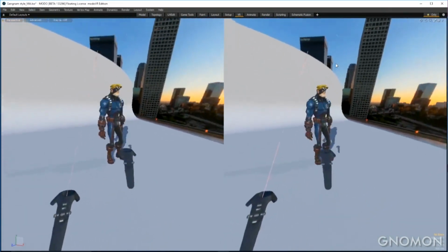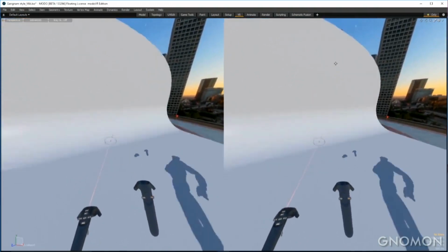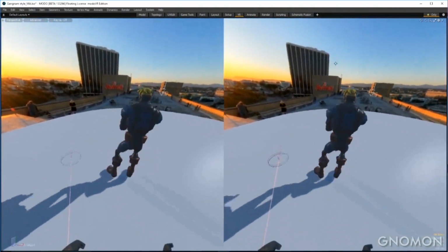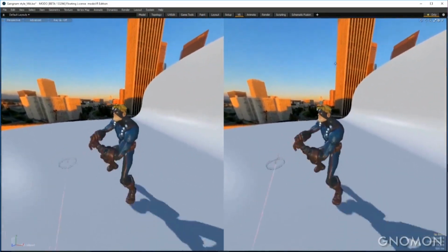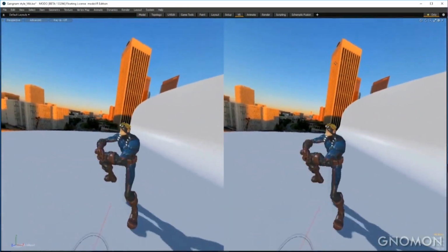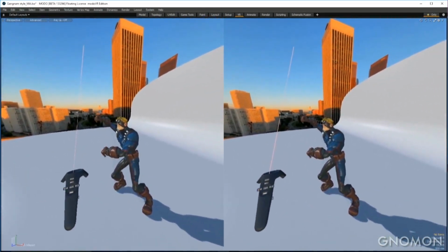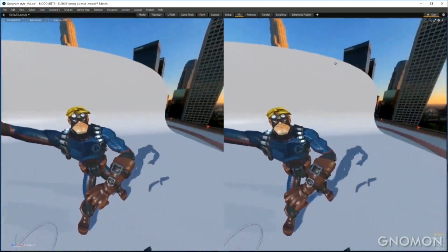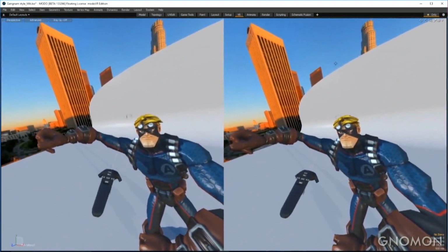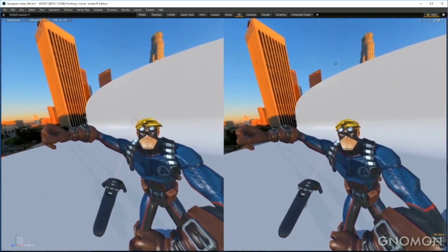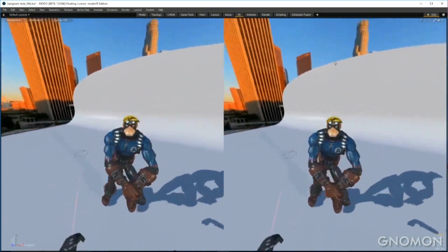And so now I can teleport around my character, take a look at it from multiple angles, which has obvious benefits for animation review. And I can even come over here to the front of the character, and I can stop my animation at any point in time. And we added a few different types of play controls here. So we have the ability to step forward and step back and choose a particular frame I want to look at. And then when I want to evaluate deformation, I just lean in and take a look at the deformation in the shoulders and decide, hey, probably need another deformer in that shoulder to try and actually get the look that I want it to actually have.